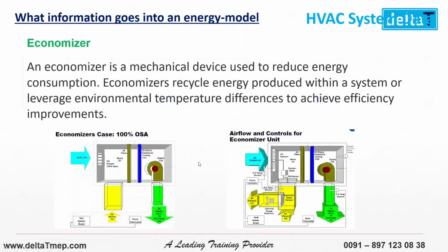So that is the economizer. You know what an economizer is? I will tell you. You have an AC. If you go to DMart, for example, even when the season is very good, January, February, still they switch on the AC because they don't have any ceiling fan. In that case, if you have this economizer type of AC, in spring season when the temperature is very nice outside, it will not recirculate the air. Instead of recirculating, it will take 100% outside air.